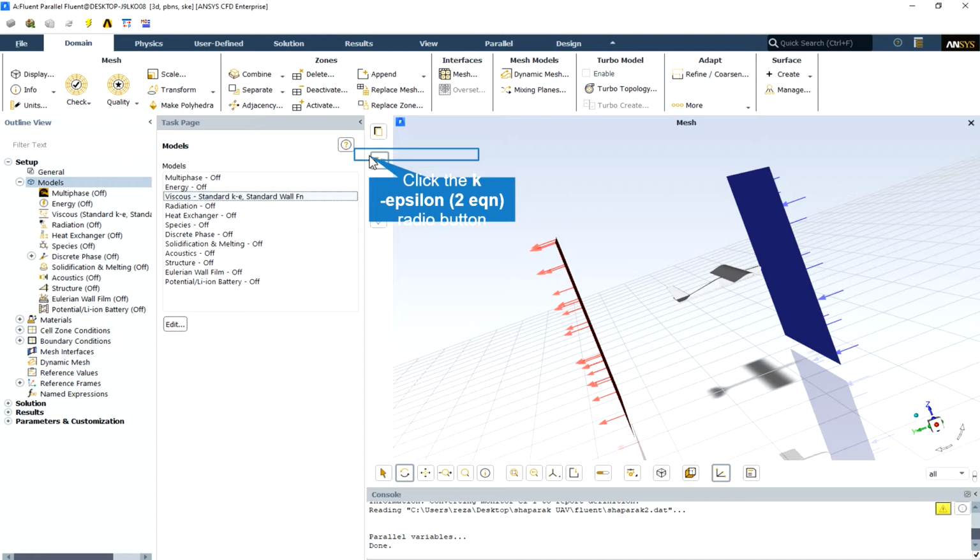The two-equation turbulence model allows the determination of both a turbulent length and time scale by solving two separate transport equations. The standard k-epsilon model in ANSYS Fluent falls within this class of models and has become the workhorse of practical engineering flow calculation in its time. Robustness, economy, and reasonable accuracy for a wide range of turbulent flows explain its popularity in industrial flow and heat transfer simulations. Also, it is a semi-empirical model.